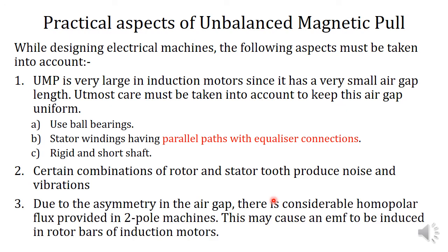And third one, due to the asymmetry in the air gap, that is the difference in air gap, there is a considerable homopolar flux produced in two-pole machines. This may cause an EMF to be induced in rotor bars of induction machines. So in order to avoid this situation, we have to use stator windings having parallel paths with equalizer connections.